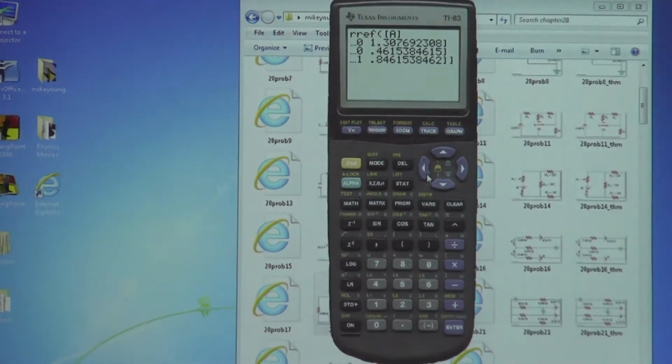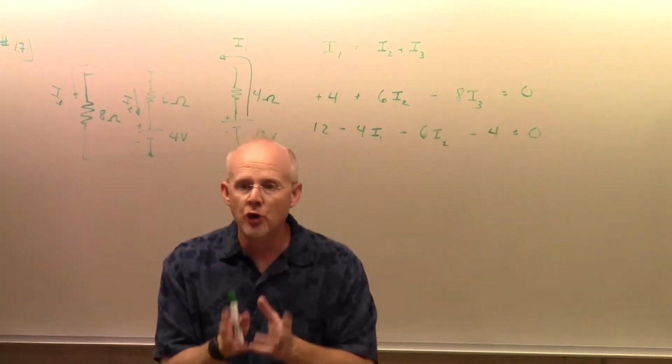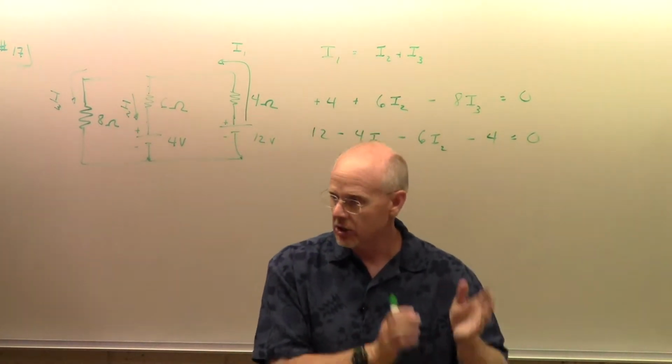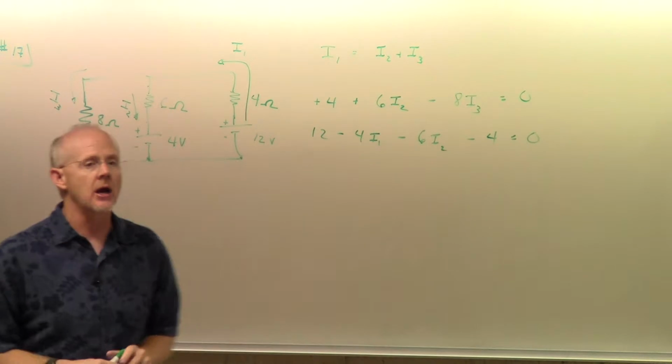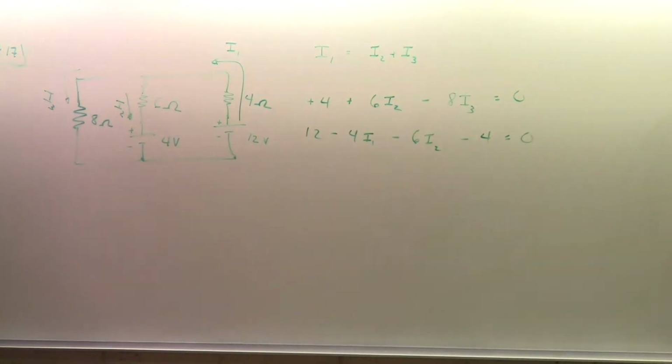And again, don't want to make a big deal of whether you were right or wrong. That's not important. What's important at the end of the problem: do you know how much current you have and what direction it is flowing? So in my case, I got all positive numbers, so my initial guesses are correct, and those are the numbers that it comes out to be.